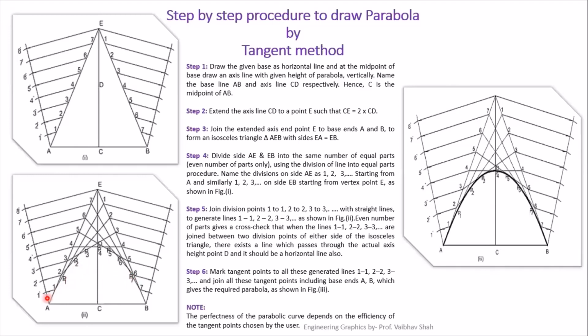You can see the idea of your curve. So almost your parabola is generated. You can see that your parabola is almost seen here in this diagram. So you just have to join it by a smooth dark line along the outer periphery of these tangents to get your accurate parabola.